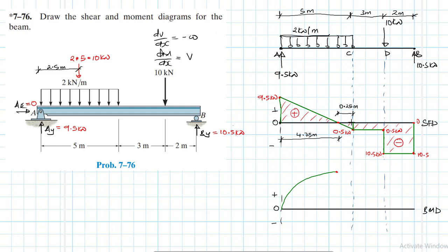Okay, so now we are in this other interval, okay, of length 25 from the point where shear is equal to 0. Okay, this point here. All right. So what do we have? We have shear that is negative but increasing, right? That's fine. So if this is the case, then we expect the slope for moment to also be negative but also increasing.